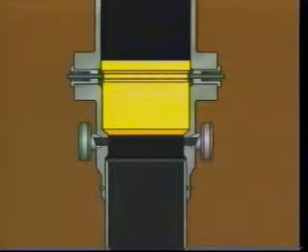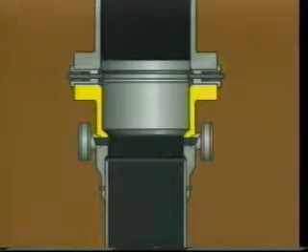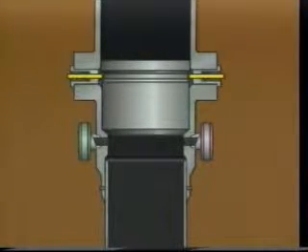The retrievable bowl protector protects the bowl in the casing head housing or spool during drilling. It is installed through the BOP and is landed in the housing or spool and is locked in place by tie-down screws or a locking flange. These screws are located in the flange of the casing spool or housing. The bowl protector is installed and retrieved with a special running and retrieving tool or a combination testing, running, and retrieving tool. The bit retrievable bowl protector is faster to run and retrieve, but it leaves the bowl exposed to the drill bit when pulling out of the hole. In addition, the driller must always remember to retract the lock screws prior to pulling out of the hole.